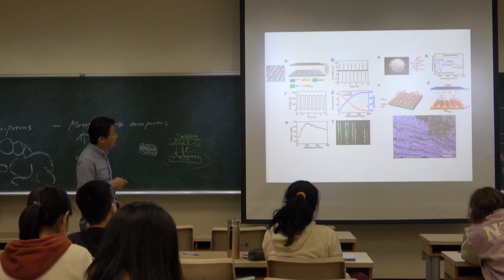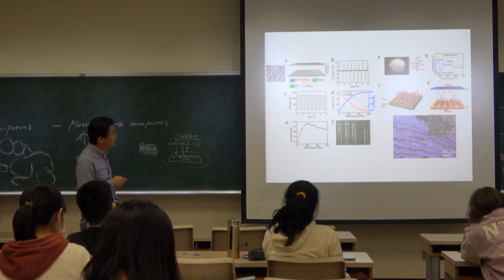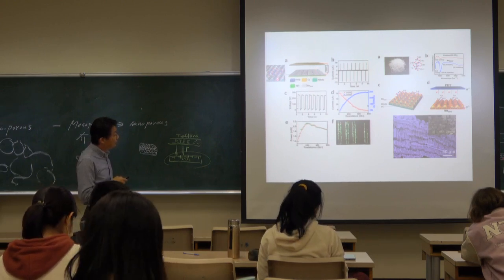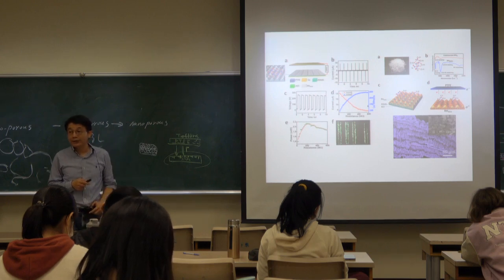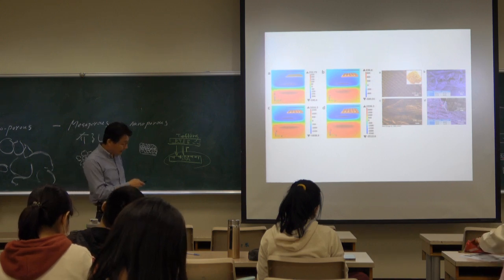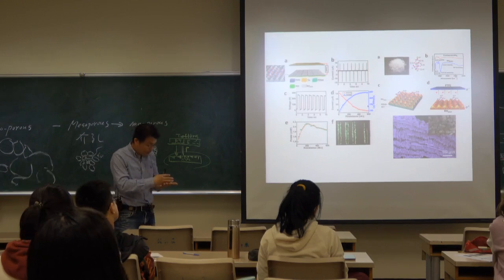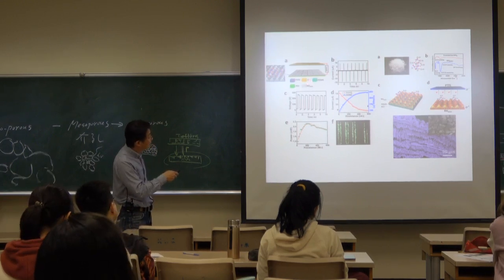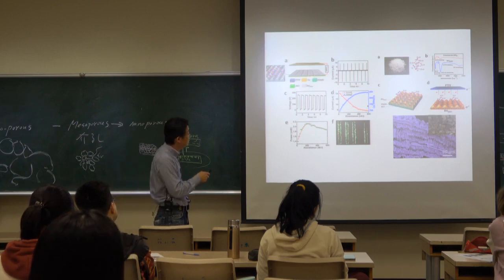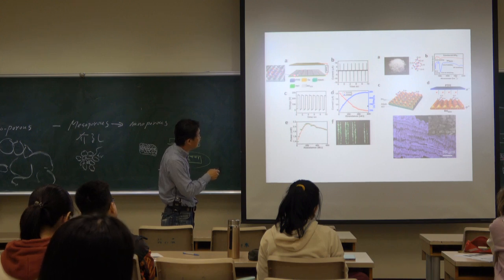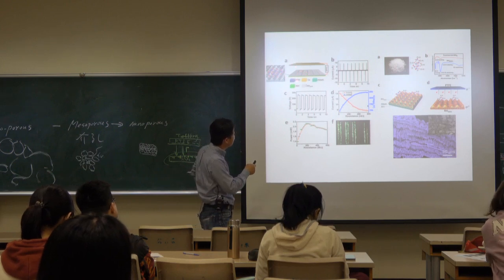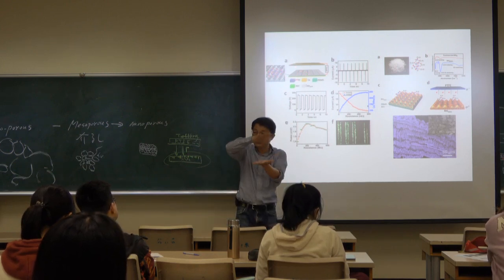So we have the sample, using the top side as PTFE and the bottom side as SiO2. The SiO2 is manufactured from rice husk. These materials we just coat on the PET substrate, just screen printing on the PET substrate. So you can see on the surface are the pores of SiO2, and the upper side is PTFE. As you can see, they are reaching each other.